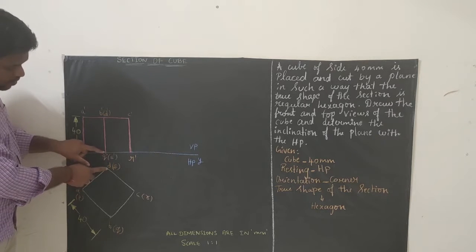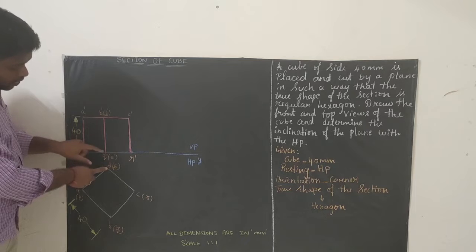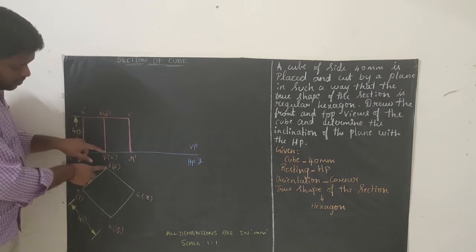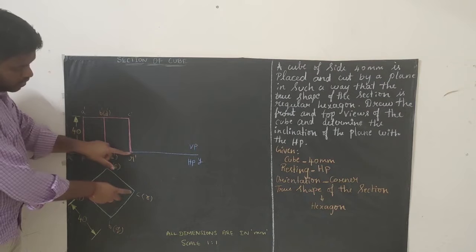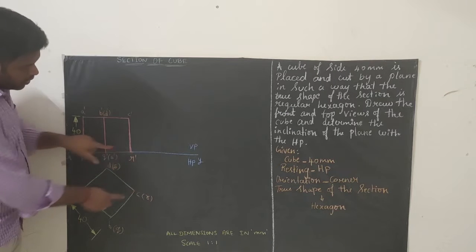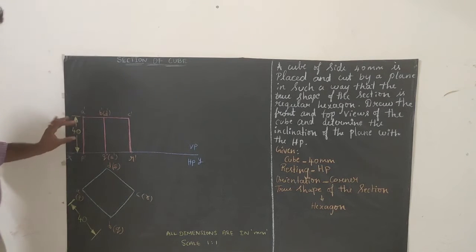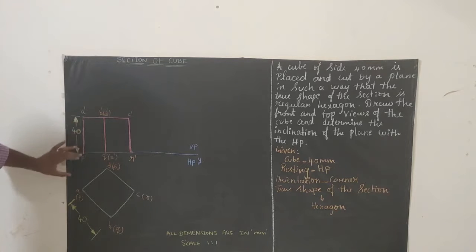Keep your scale here parallel and perpendicular, vertically. You just keep your scale, just try to get the point here. Keep your scale here and try to get the point. 3 points on the reference line, and you know very well height of the cube is same, so 40 mm. So for 40 mm you draw a line and try to draw this box.